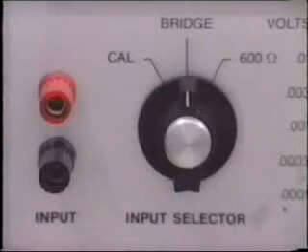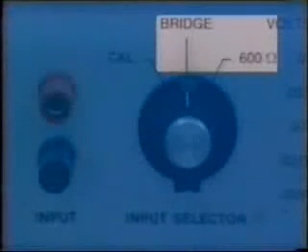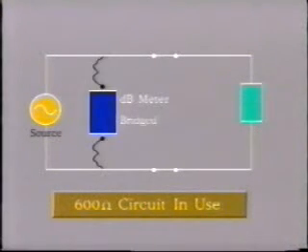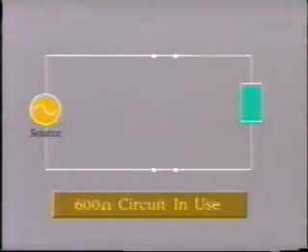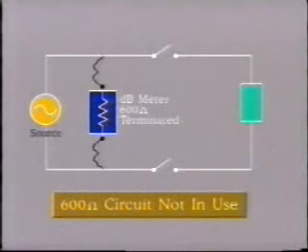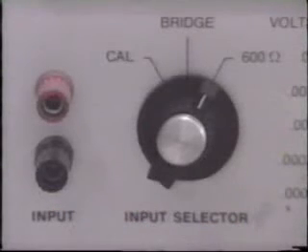Many dB meters are provided with a selector switch marked bridged or terminated. The bridged selection should be used when you wish to perform dB measurements on a circuit which is already properly terminated. In the bridged position, the impedance of the meter is high, therefore having negligible effect on the circuit. However, in some cases, you may wish to measure the signal strength directly from a transmitter or signal generator with the outgoing circuit disconnected. For this purpose, the selector should be switched to the terminated position.